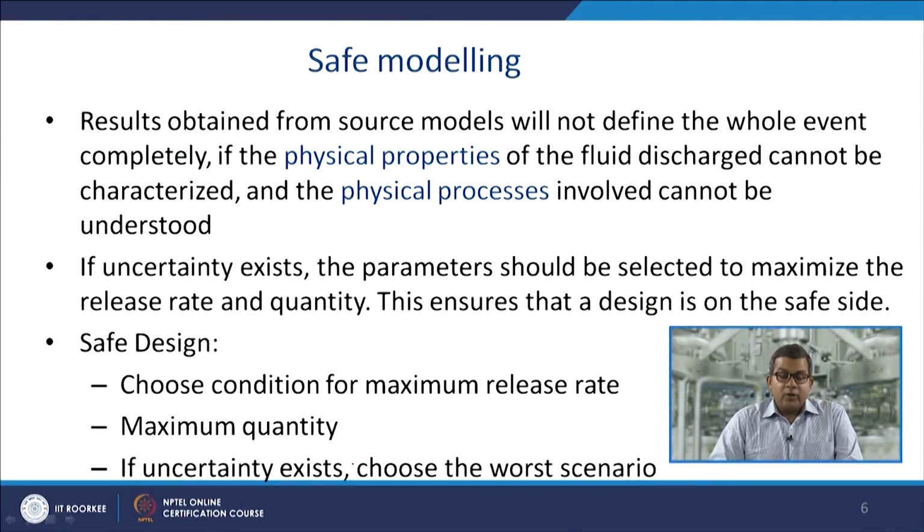It is just like if you wish to design things, you may take the LPG cylinder, the domestic LPG cylinder, and take the maximum quantity, that is, the cylinder completely filled, 14.2 or 14.5 kilograms as applicable to the cylinder. Now the worst scenario is that the cylinder will burst and the entire LPG will escape from the cylinder and catch fire. So this is the worst scenario.